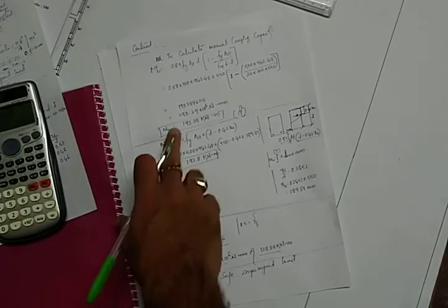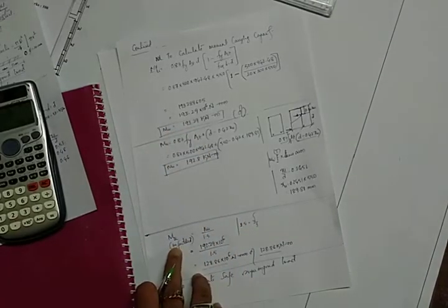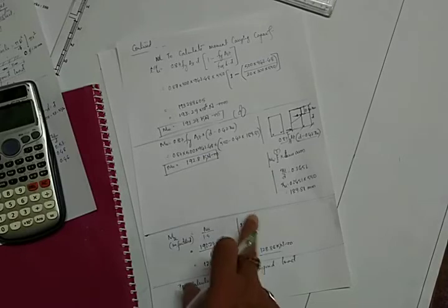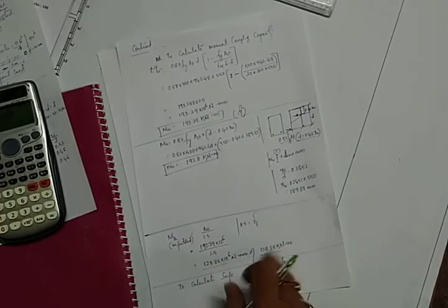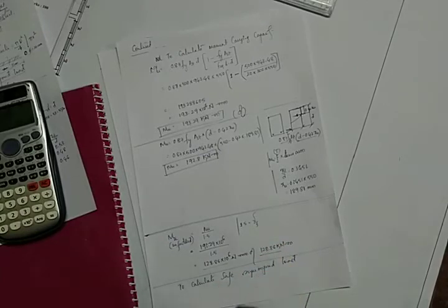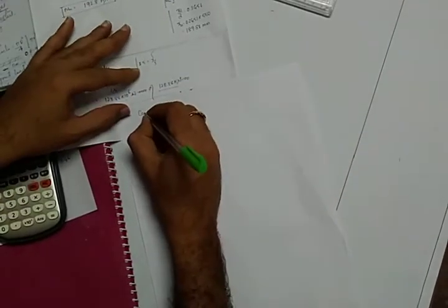So we will calculate mu, and then after calculating this mu, we will calculate safe unfactored moment by dividing by factor of safety, that is 1.5. That is known to you from limit state method. It is well known that factor of safety is added. So therefore we are dividing that 193.29 into 10 power 6 by 1.5. It comes around 128.86 kilonewton meter. So after calculating this moment, I have to calculate safe superimposed load. Therefore, see from the next page. So again it is continued.